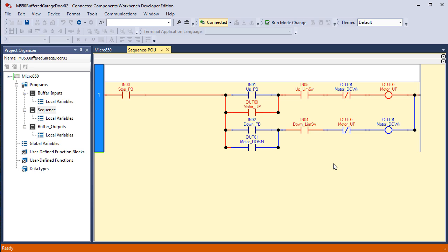Now, if the motor was not running, let's stop it right now. And that's input 0. So I pushed input 0, and you see that it dropped out the motors. Even if you didn't see input 0 go false, I'll hold it down a little bit longer. See, it went false. It only has to be off. In other words, that normally closed push button only has to be open for one program scan when the inputs are updated, and from there on it's a done deal.